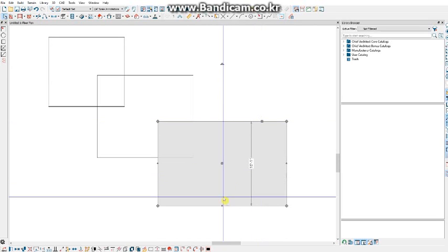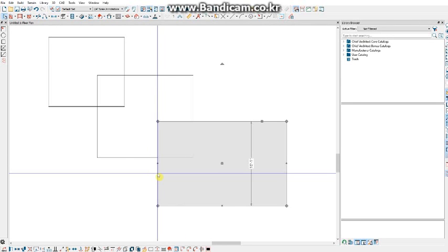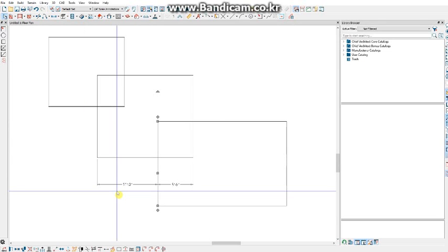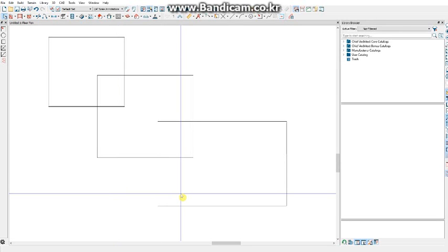When you click on an object or select it, the Edit toolbar shows up at the bottom. This toolbar is specific to the object type you have selected and holds all of the tools that you can edit that object with. You can remove any individual line from a polyline by selecting and activating that line and then clicking on Disconnect Selected Edge. Now it will treat that line as one individual line. If I hit my Delete key, it'll only delete that line.